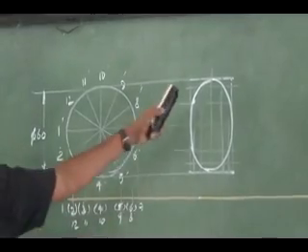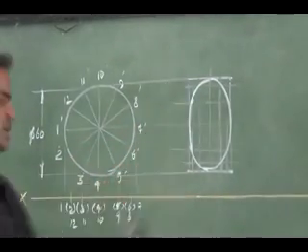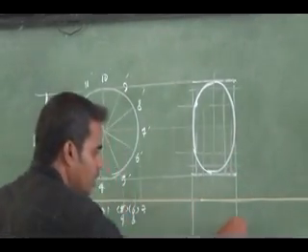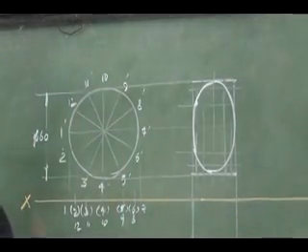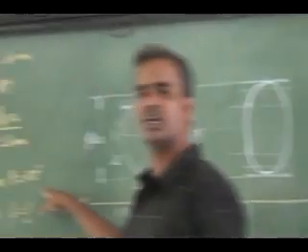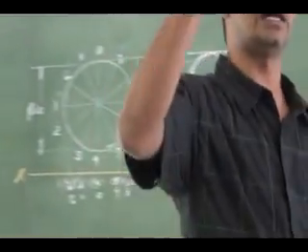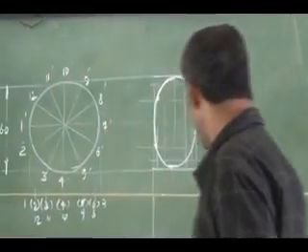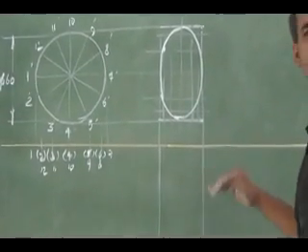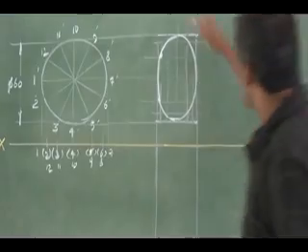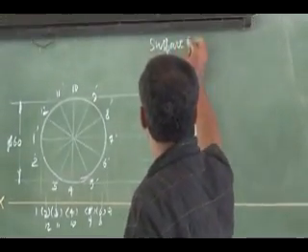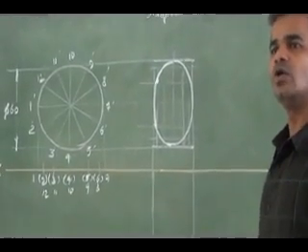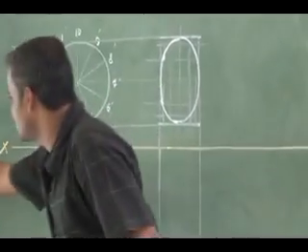So for this, to get this perfect ellipse, to what inclination do I have to tilt? 35 degrees. You see here, that inclination is not given. You see here, the surface inclination is 35 degree. It is theta, with respect to HP. So here, whatever inclination below the reference line you are going to have, that is going to be the surface inclination. As for this problem, whatever surface inclination you have here, it is going to be phi. So that surface inclination is phi.